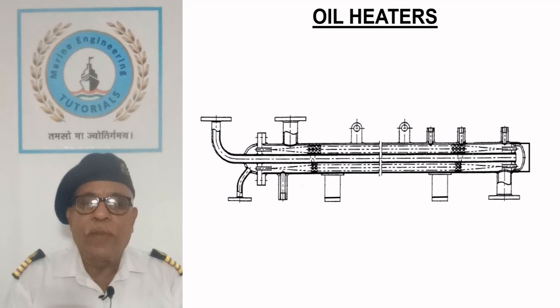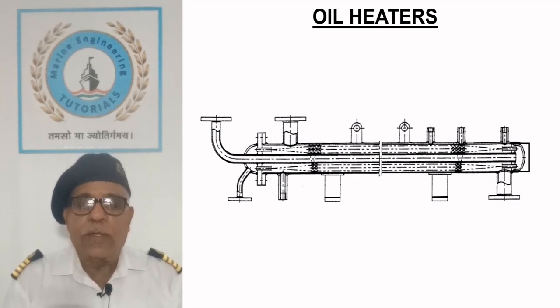Oil heaters. Oil heaters are used on the ships for purification of fuel and lubricating oils. In addition to these, heavy fuel oil used in boiler furnace or in diesel engines require necessary preheating in order to bring down the oil viscosity within the desired range.